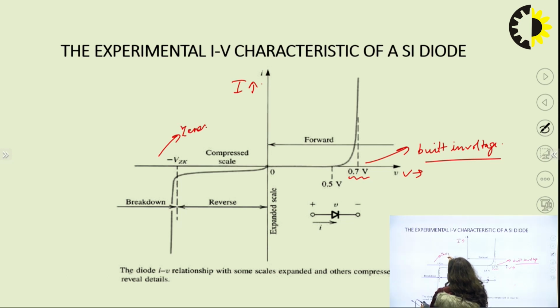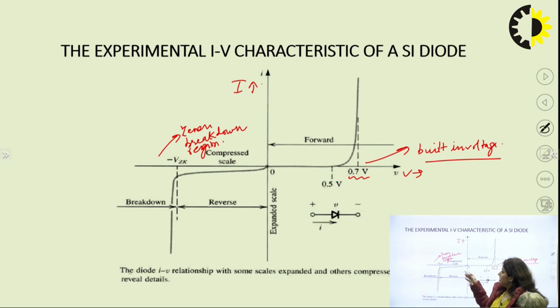So this is your Zener breakdown region. At the Zener breakdown region, we have a drastically sharp increase in the current in the negative direction. We can draw this characteristic easily in the lab by taking readings of current against voltage in forward biasing, and again in reverse biasing, and we can draw the characteristic curve for the PN junction of the silicon diode.